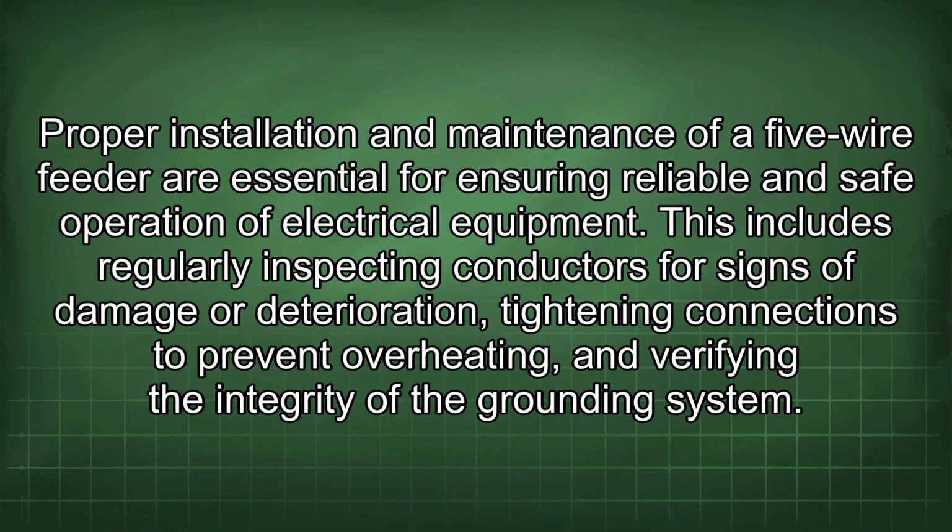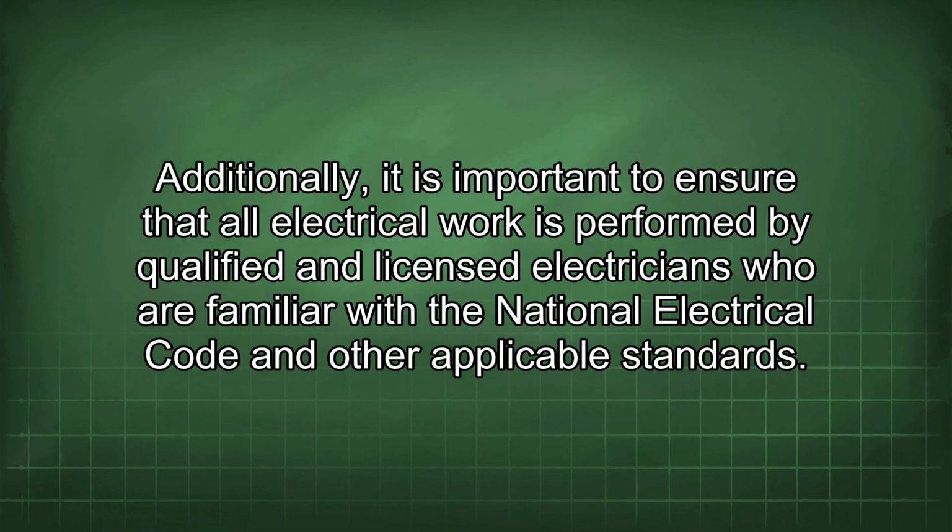Proper installation and maintenance of a 5-wire feeder are essential for ensuring reliable and safe operation of electrical equipment. This includes regularly inspecting conductors for signs of damage or deterioration, tightening connections to prevent overheating, and verifying the integrity of the grounding system. Additionally, it is important to ensure that all electrical work is performed by qualified and licensed electricians who are familiar with the National Electrical Code and other applicable standards.